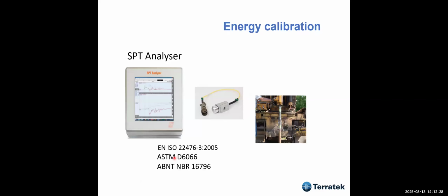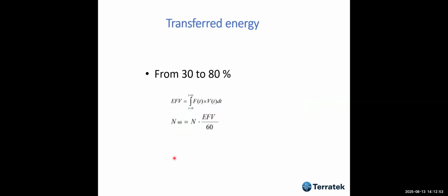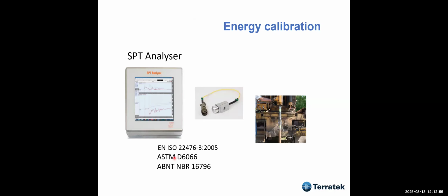One requirement that's new: standards like the European, ASTM, and others now require that the energy of the SPT should be calibrated. I mean, every rig should be calibrated once a year. And in order to do that, we use this kind of SPT analyzer.